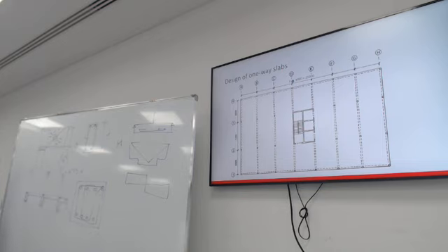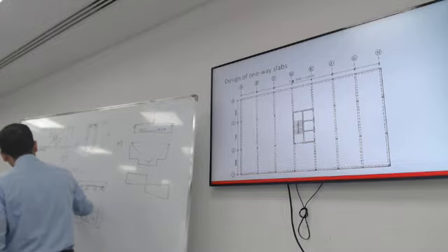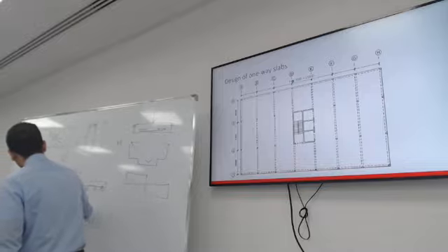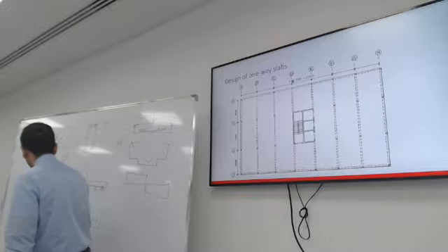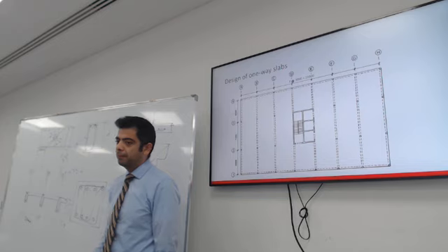All right? How do you reinforce the slabs? You can think of it as like a beam, but very shallow. It depends on the spacing or the span. This is the span. We can estimate a thickness of the slab. This is T slab, or the thickness of the slab.